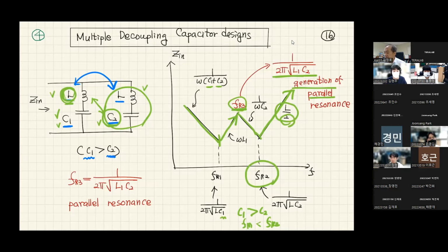So in this simple circuit model, what I'm saying is that we're gonna generate anti-resonance frequencies. This series resonance frequency is very helpful for us to make a low impedance power distribution network. But because of these anti-resonance frequencies, we're gonna have higher impedance, and usually this anti-resonance frequency is a very source of EMI.